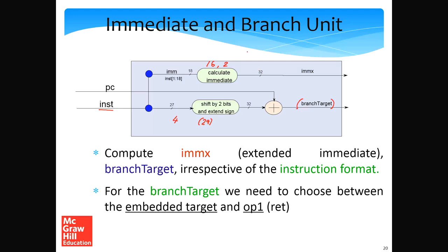So just to repeat, if it's a default modifier, then what we do is that we take the 16 bits specified and we essentially extend its sign with the sign bit, we sign extend it. So this is a default modifier. If it's the unsigned modifier, what we do is that we write the 16 bits in the lower 2 bytes, and in the upper 2 bytes we just write zeros.